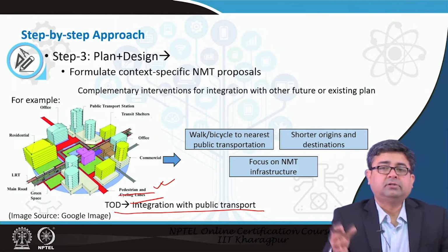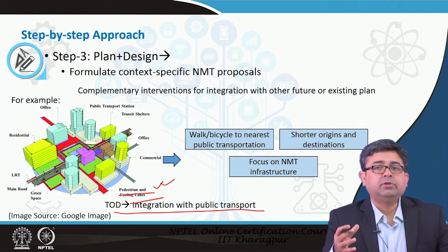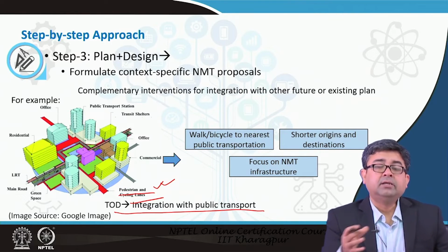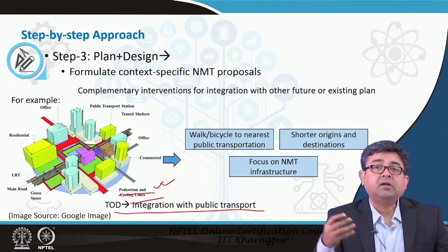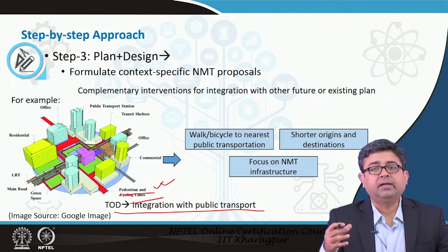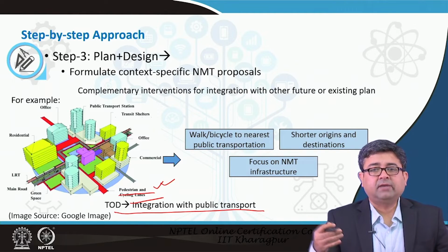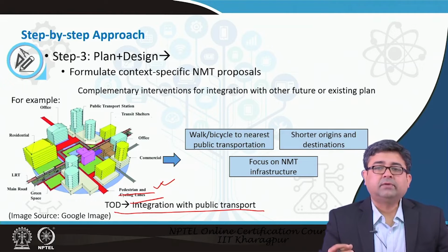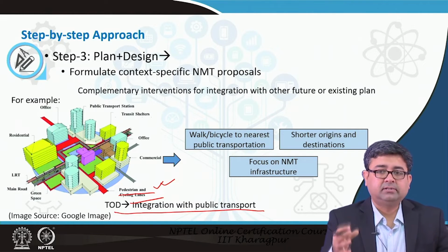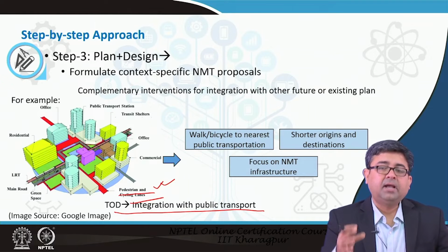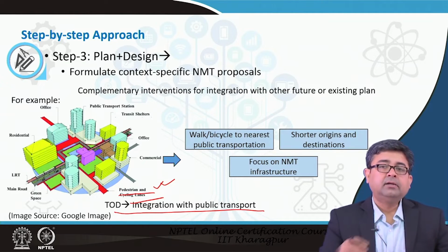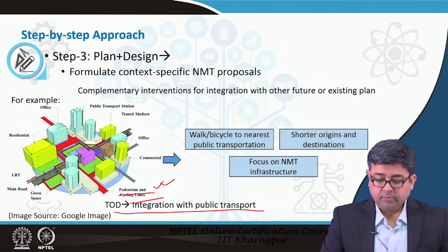That will not solve the purpose, although many a time you will see some isolated sidewalks, but they are part of the process. They may have built it in phases. The first phase might have been built, and the second phase might not have taken off. That is why you see an isolated sidewalk or an isolated bicycle path. However, if the plan is to have the isolated sidewalk, then that is not a good plan. The plan should have an integrated solution for all the NMT modes.